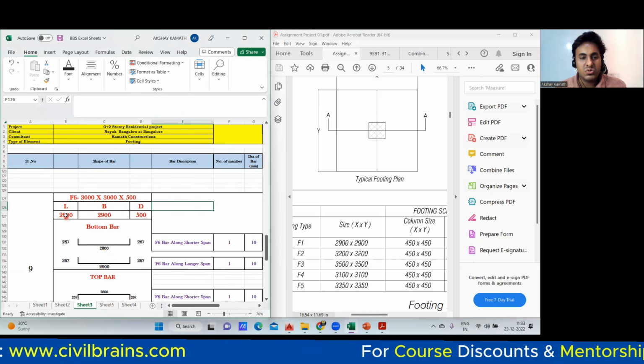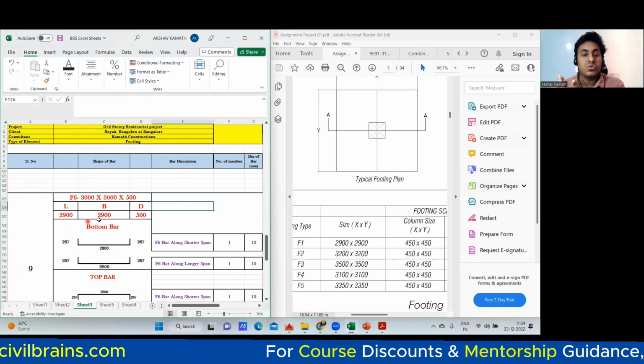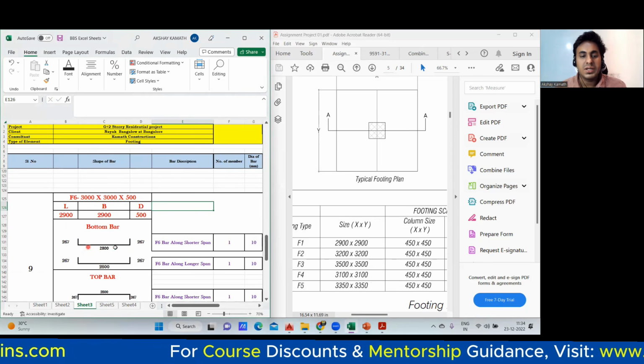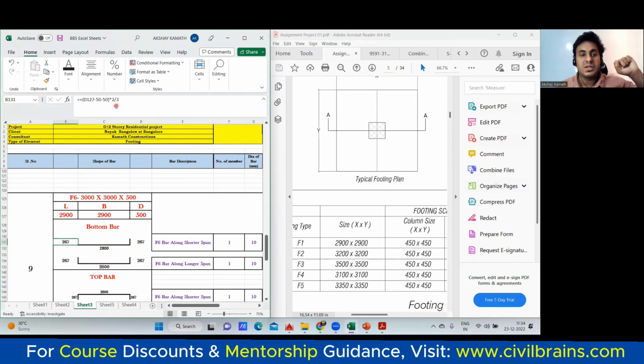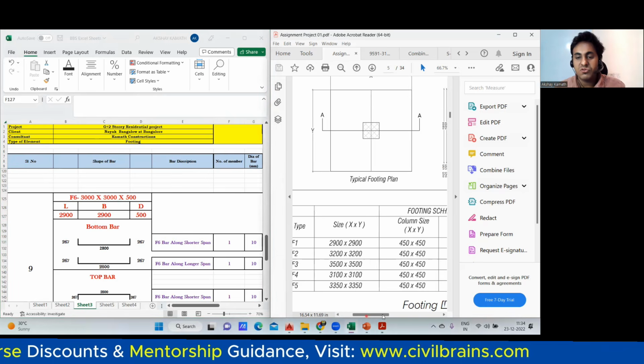Your cutting length is 2900 minus left side 50, right side 50, which is minus 100. So 2900 minus 100 is 2800. You know that. By default, you got the answer. And for the depth, we know it is 500 minus top cover minus bottom cover, into 2, plus 35 twice. Same thing I have done. You got it as 267. Fine. Now come to the reinforcement part.